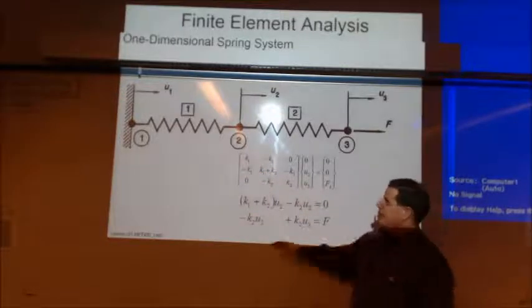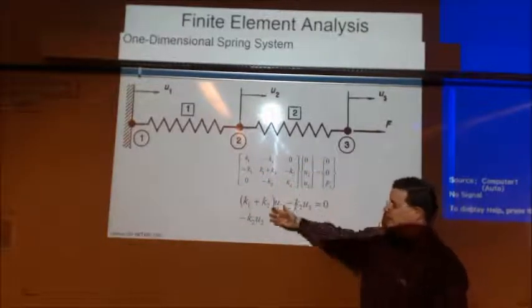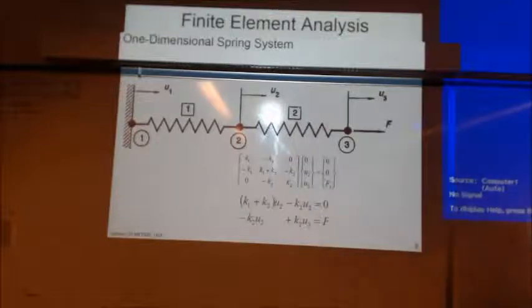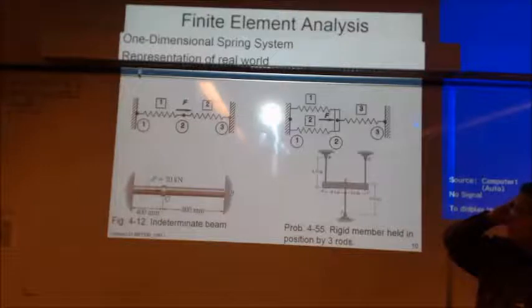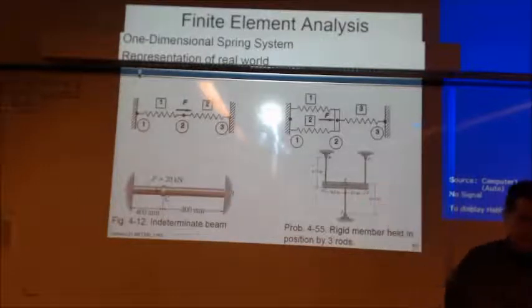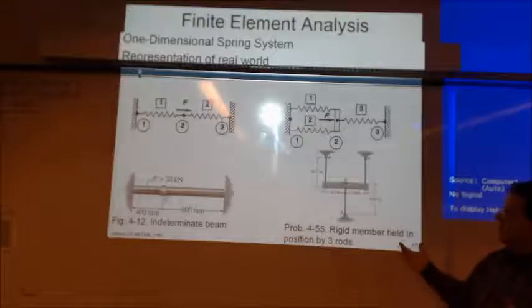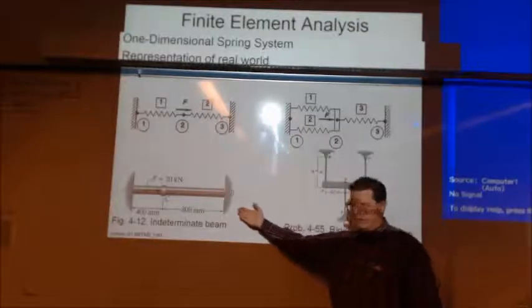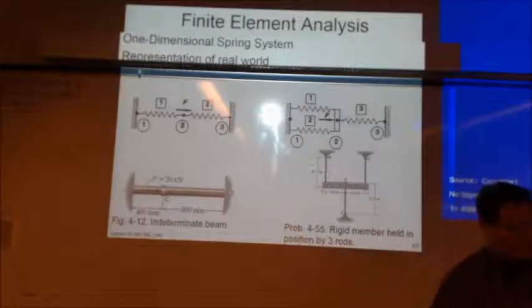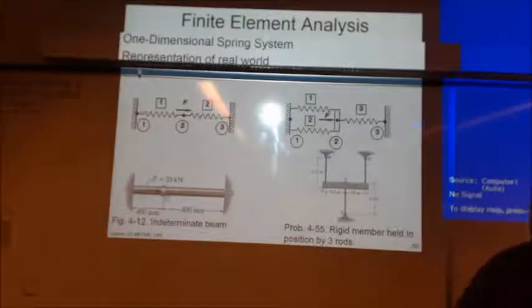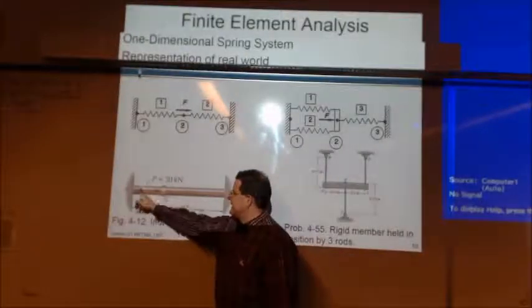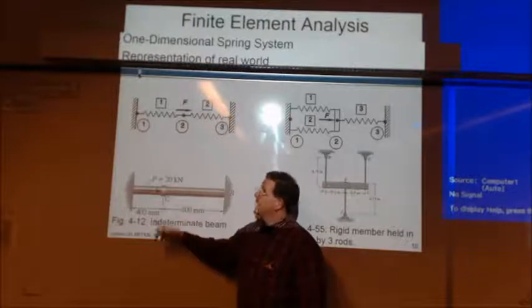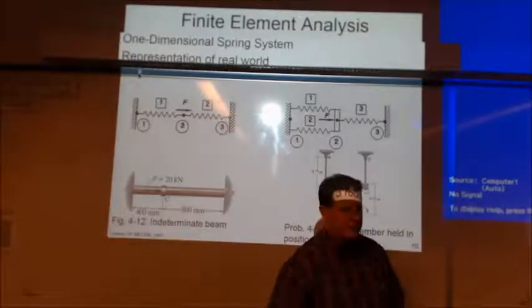If we had a more complicated system, obviously our system of equations would be bigger and more complicated, but it would set us up. We can use this simple one-dimensional spring simulation to approximate some real forces in a real application. We're going to break this into two nodes and say this is one element, this is one element, and we can use this to determine how much that's going to deflect, right?